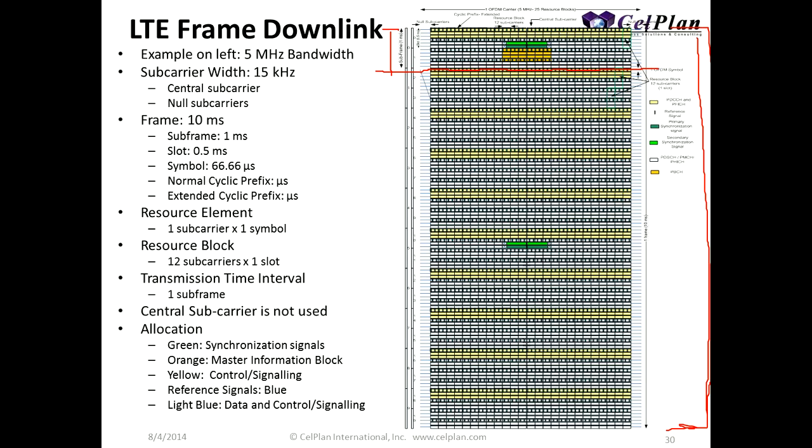What this means is that everything is scheduled within a TTI. So in the TTI you have one area depicted in yellow, and this area carries the mapping, the information of where in the remainder of the TTI the data is placed and to whom it is directed. So basically all the mapping is for one TTI, and all the data mapped is sent inside the TTI. The next TTI starts from scratch again, and so on. So you have 10 TTIs per frame.